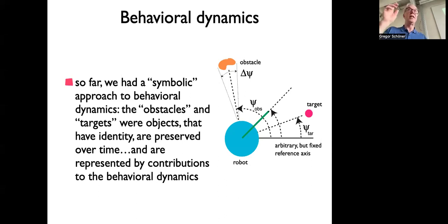This is actually routinely done by sensory processes that deliver information about that. For instance, for those of you who know this sort of thing, you would have Kalman filters that integrate the current sensory information with previous estimates. And for every obstacle, you would have a Kalman filter. And if a new obstacle arises, you have to start a new Kalman filter.